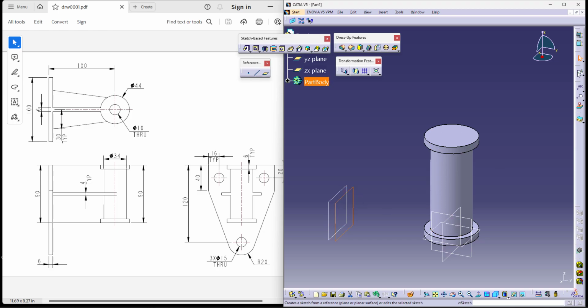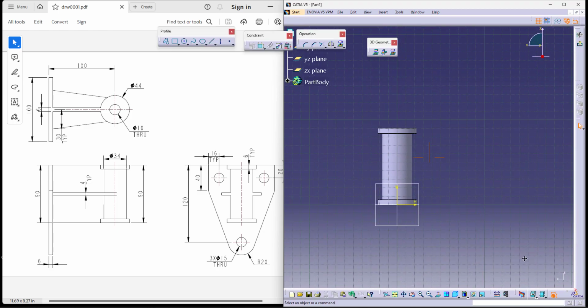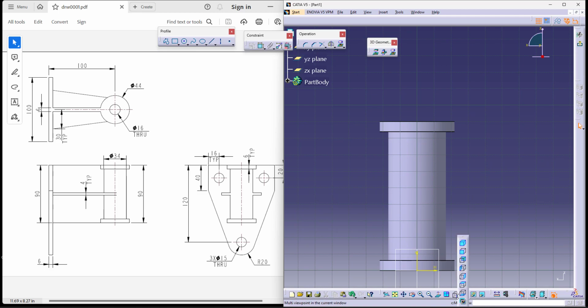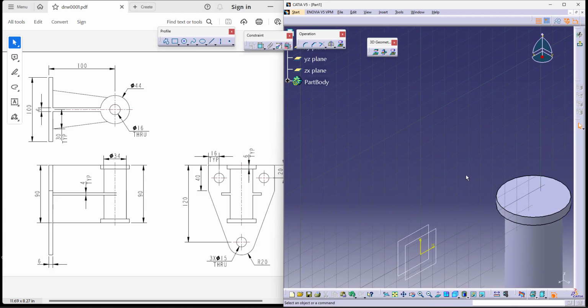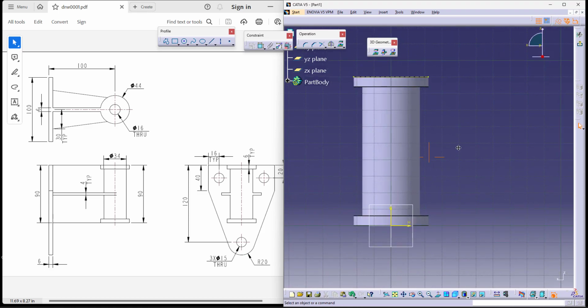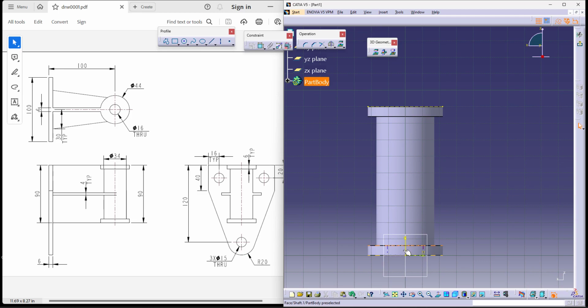So again, on this plane, you can directly try to make a sketch. If you're not comfortable, you can go into your right view and check how the model is. This is the correct right view at the moment. I can also go back into the isometric view to show you the model. This is my reference which I'll be using. From here, the center is the axis. From here, I'd like to take a small rectangle by maintaining symmetry.